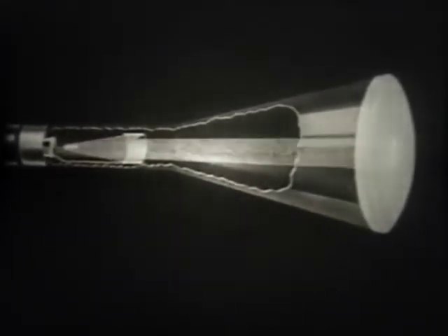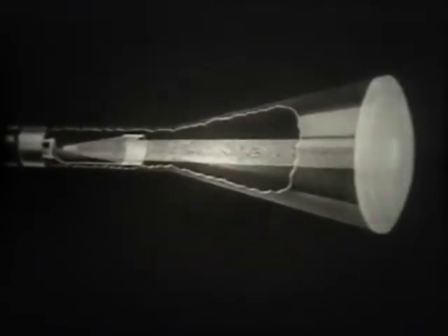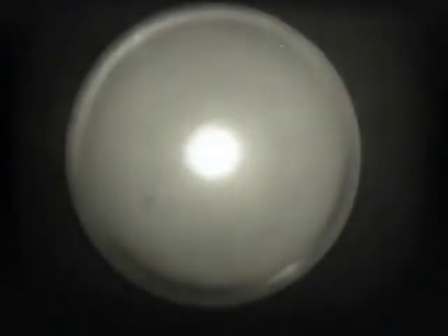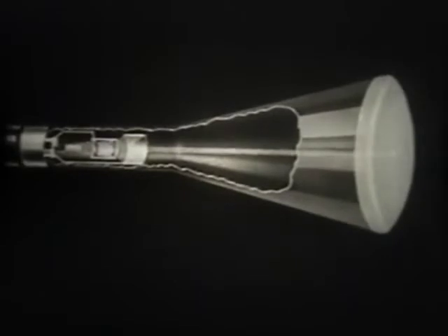The screen, the front inner surface of the tube, is a coating of fluorescent material that glows at the point where the stream of electrons strikes and excites it. So on the front of the screen, a round spot of light appears. The spot, however, is large and fuzzy. For practical purposes, we need a sharply defined spot. The focusing anode helps do this job by concentrating the stream of electrons into a small beam before it reaches the screen. The electrons converge and strike the face of the tube as a sharply focused spot.